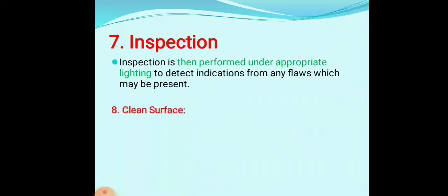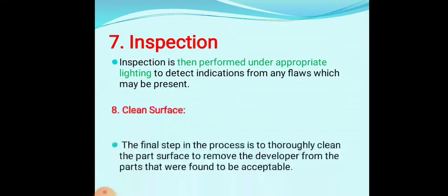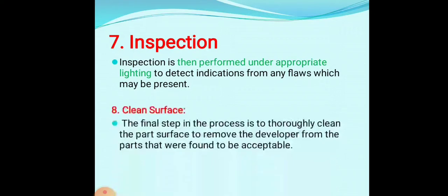And then the last one, the eighth step, is cleaning the surface. After the testing is performed, we clean the surface. That is the last step of liquid penetrant testing. We completely clean the surface of the penetrant liquid as well as the developer.